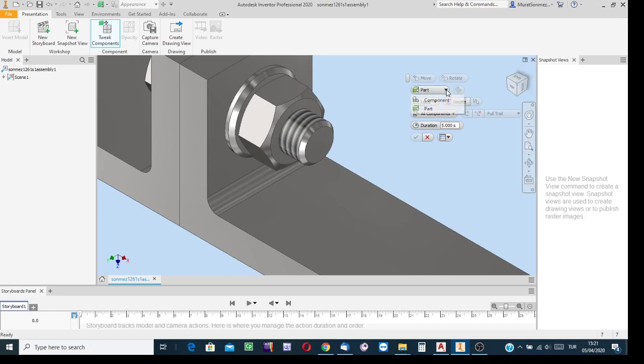And then, drop this list. I am going to prepare this animation file not for the object but for the components of the object. So select the component option, and then which component? First, I know that the nut is to be disassembled. Indicate the nut with a click, and after the click you can find these two buttons ready to select.